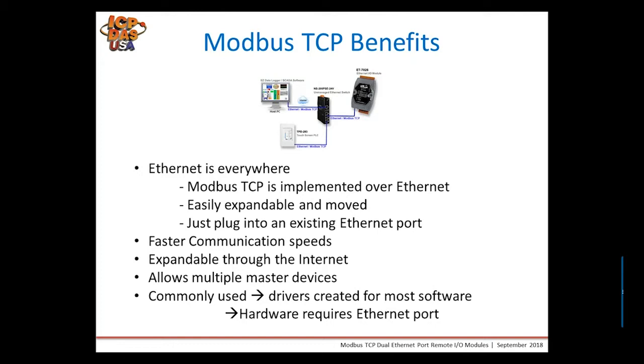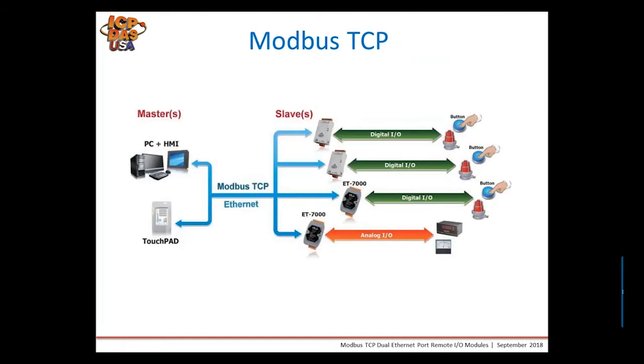You could allow multiple master devices as opposed to Modbus RTU, so like a SCADA system and a PLC can both read the data from the Modbus TCP slave device. And drivers for most software are available for both Modbus TCP and Modbus RTU.